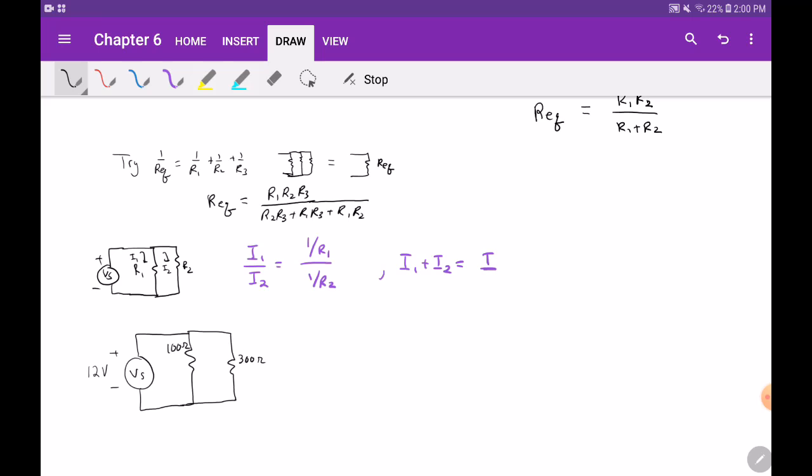So our goal is to find the voltage drop across each resistor, which is easy. That'll just be 12. You gain 12 every time you go around the loop, so you have to lose 12 coming from here to here. You also have to lose 12 volt when you go around this other loop. So that one is easy. Then I want to find the current through each resistor.